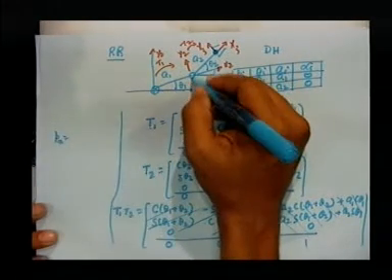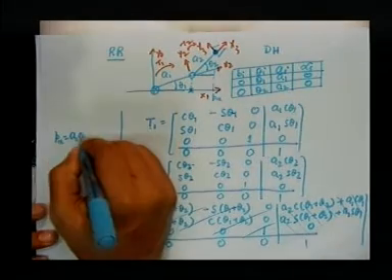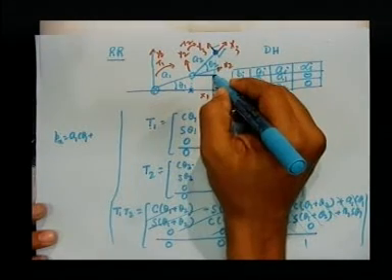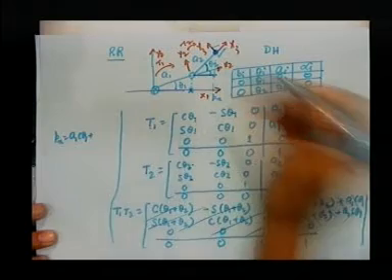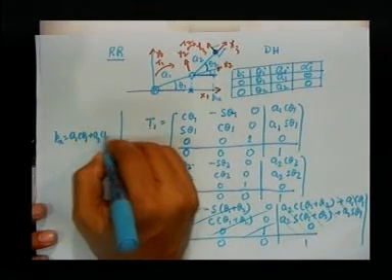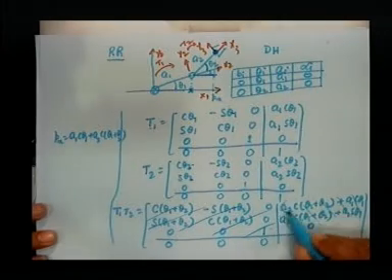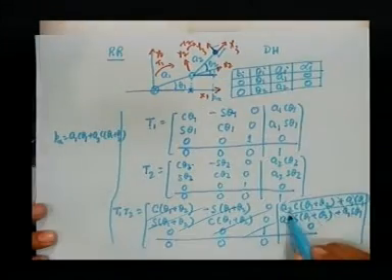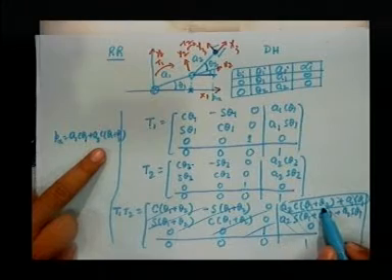is equal to what? This component. So, this is A1 cos theta 1, plus this component. What is this component? This angle is theta 2, this angle is theta 1. So, this component will be A2 cos(theta 1 plus theta 2), and you see this is the x component of this point. So, Px is A1 cos theta 1 plus A2 cos(theta 1 plus theta 2).